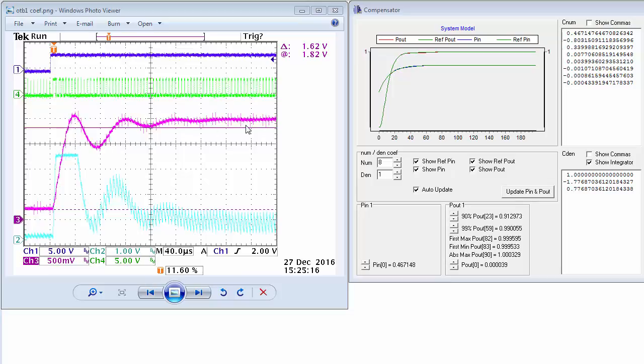Note that the first PWM cycle is very wide, followed by narrowing PWM pulses, nearly zero width, and occasionally I have found a completely missing pulse here in this time slot. The system current clips here and oscillates. The output voltage also oscillates before settling.